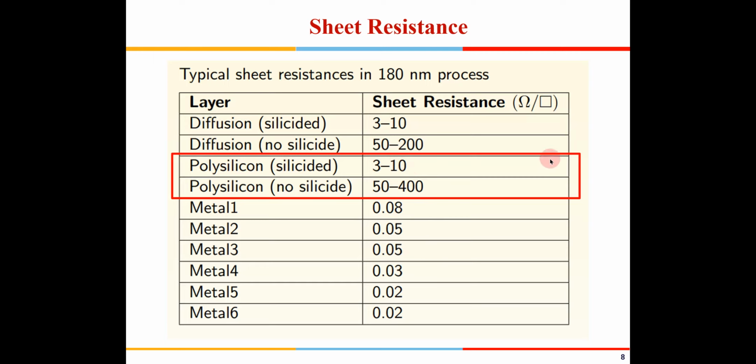So a better option would be to place a wire and then use a metal to interconnect. If two transistors are placed far off and you need to connect the gates of those two NMOS, both the gates being poly, you can still draw a metal one interconnect and use a wire, rather than stretching the poly to make a long wire out of polysilicon. Okay, so you need to be careful with that.